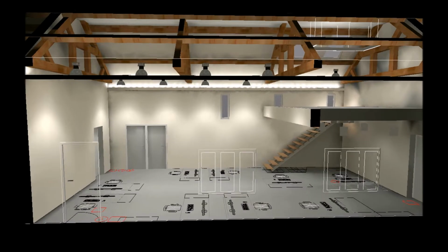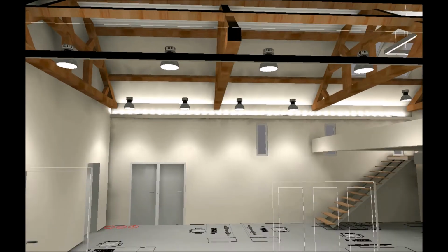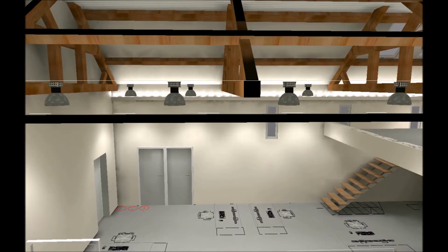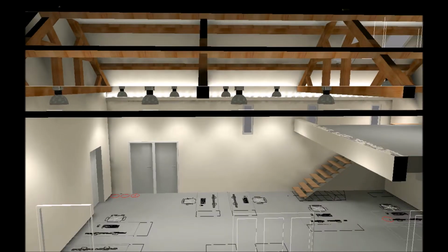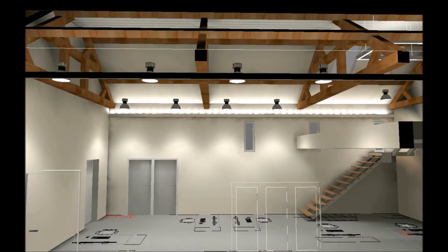I've put in some LDT files to represent those IKEA lights that you've put in there, and then I've gone with the design brief of these industrial looking but kind of decorative high bays, and it worked out as I thought, as we discussed on the site, where we would need 2 rows of 4. So, and that works out nicely for the lighting level, and it meets glare regulations too, which is what we want.